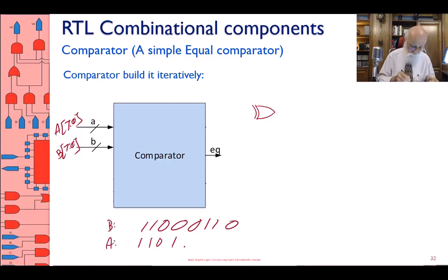You have two binary numbers, and you start from the left-hand side. This is the algorithm I'm presenting, and then I show you the hardware for it. Just coming in, since I haven't seen anything to tell me that A is not equal to B, I assume A is equal to B.